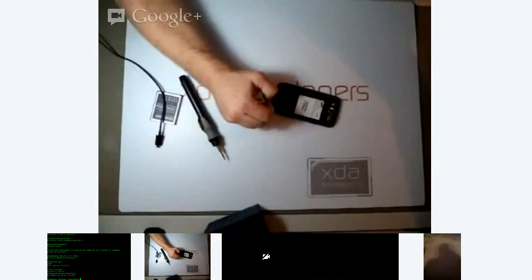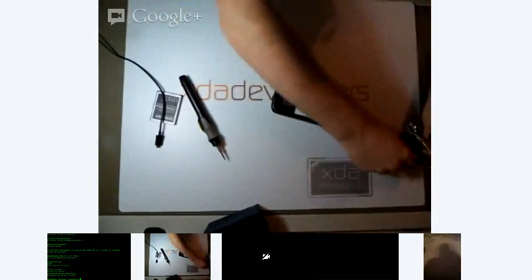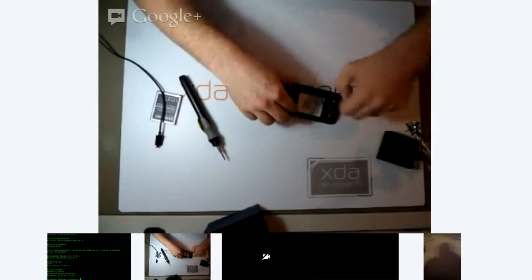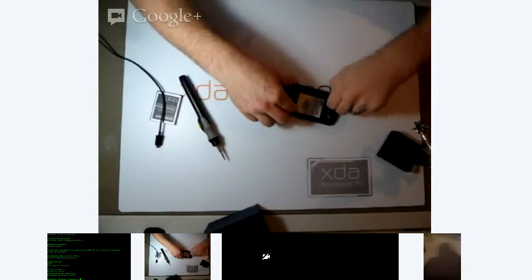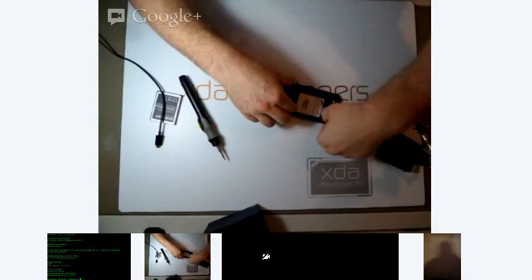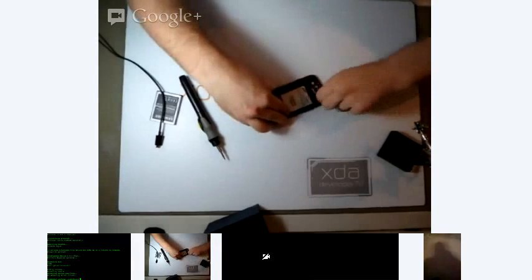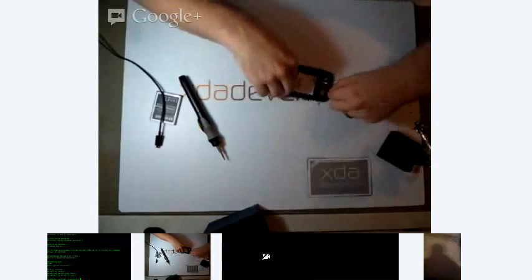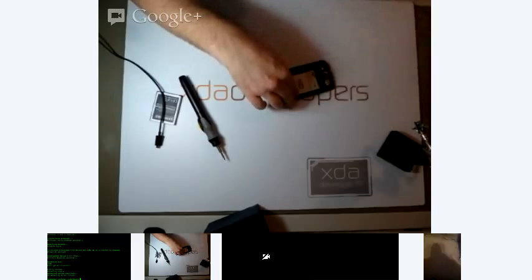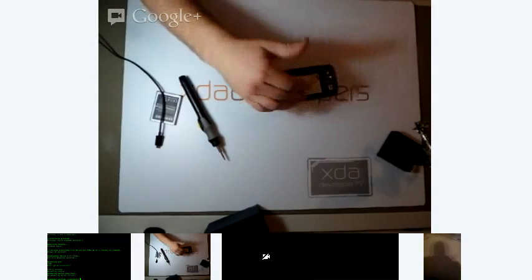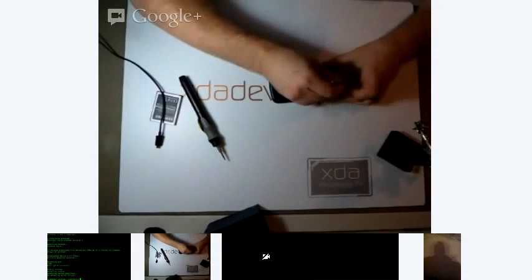It's got a very solid chassis on it, and the UART ports are very accessible. The eMMC disable is very accessible, and because it's got a metal chassis, I can actually glue something to the outside of it and not really have to worry about it falling off. I ended up putting a little button on so I can switch modes between the normal Galaxy Camera and the Open Galaxy bootloader.